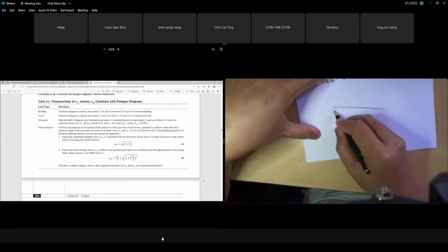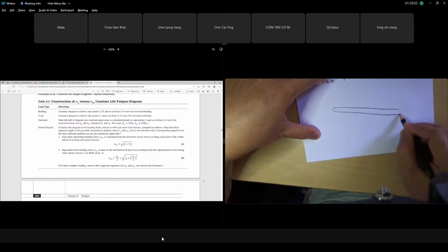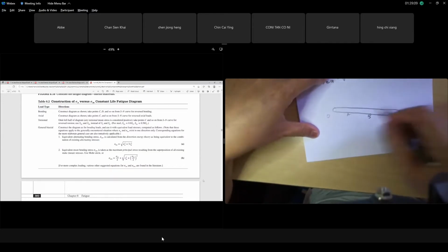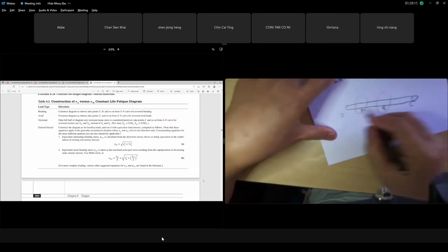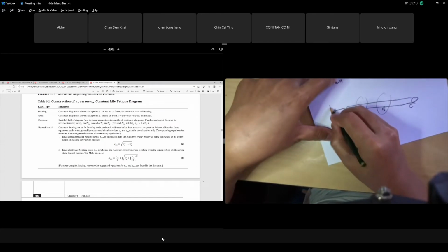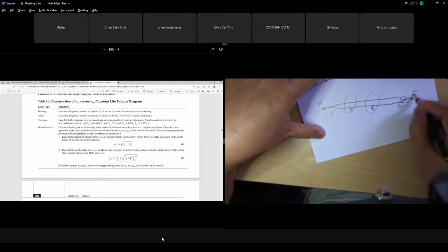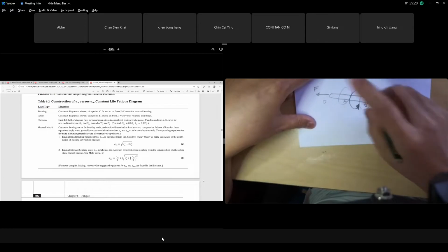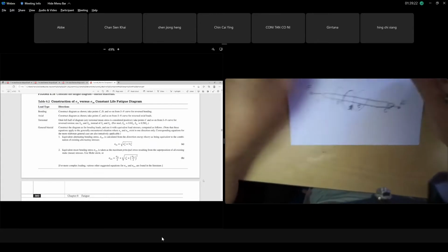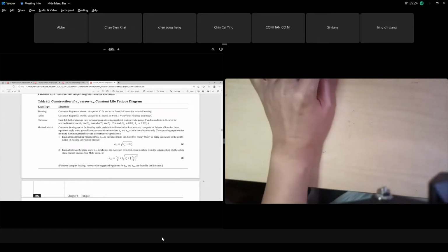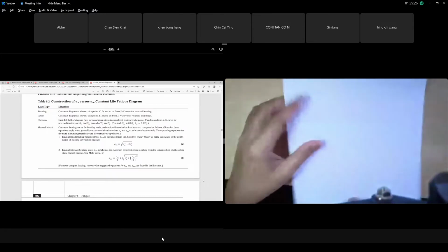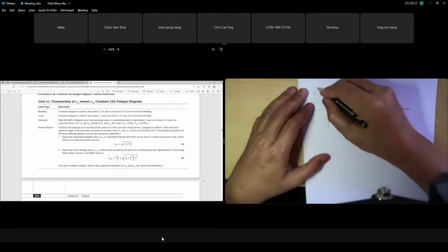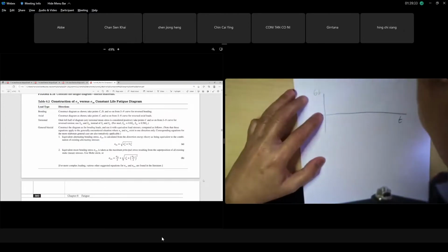This is your shaft, OABC just now, where you have the pulley, and you have axial load just now, F 2000 Newton, and the shaft is rotating. Remember, guys, the shaft is rotating. Kalau kita plot bending through time, this is sigma bending through time, the shaft is rotating.